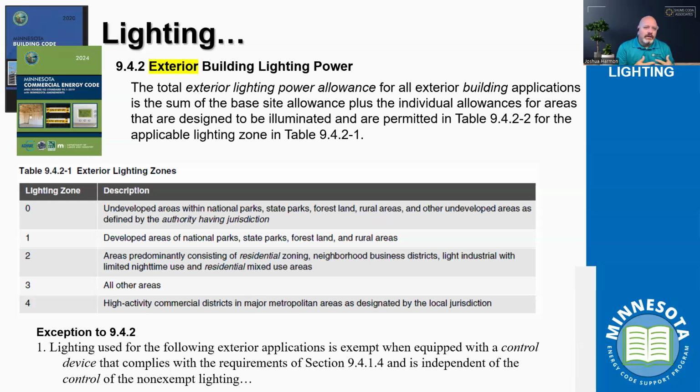So the question is, would electric overhead heating be included in this calculation? No. That would be completely different. This is only lighting, right? This is just for task light, general lighting that we associate. Now, and this is not to go on a digression, but the IECC starts to delineate general lighting from task lighting versus some other types of lighting. You get a little bit of that in the space-by-space method, but this section 9 is specifically lighting. So the electric heating calculation is independent of my lighting fixtures.